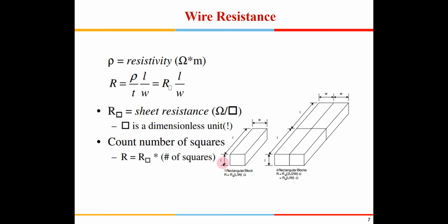So why keep this T here in this equation? We have defined a new way of defining the resistance, which is known as the sheet resistance. That is nothing but rho divided by T. So this T is also taken care of. Rho divided by T, where rho comes from the metal which is being used.